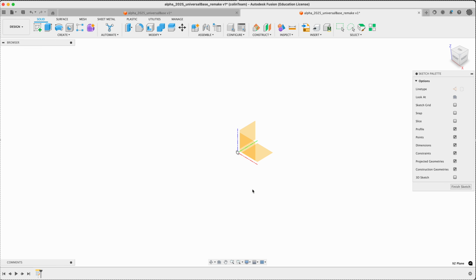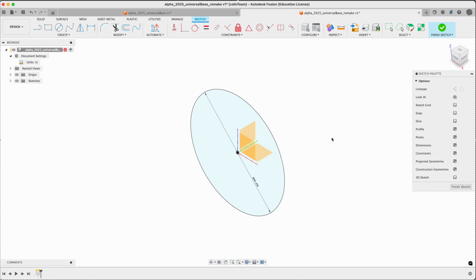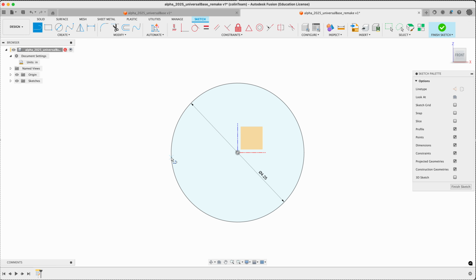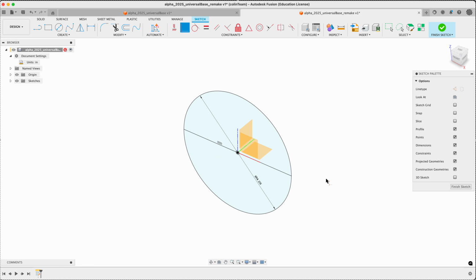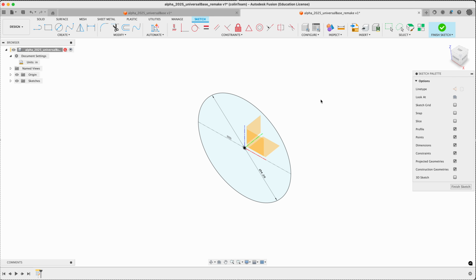Insert sketch. We're in inches. A sphere is based on a circle, and it's 2.125 times 2, because that was our radius. Now we want a diameter. I'm going to make a sphere, so I need a line to go through that to make a rotary axis. Make it horizontal and put it through the origin. It doesn't have to be centered because we already know that. If you wish, you can make this a centerline. You still get the good regions.